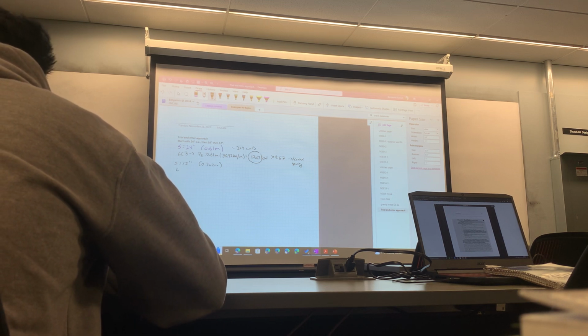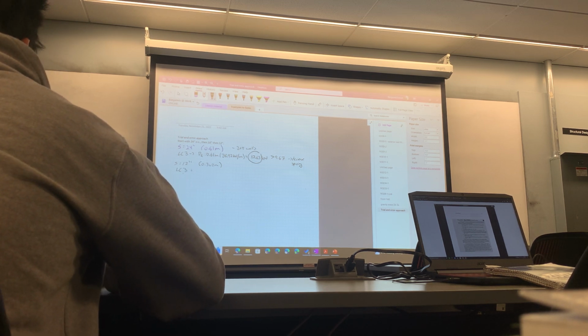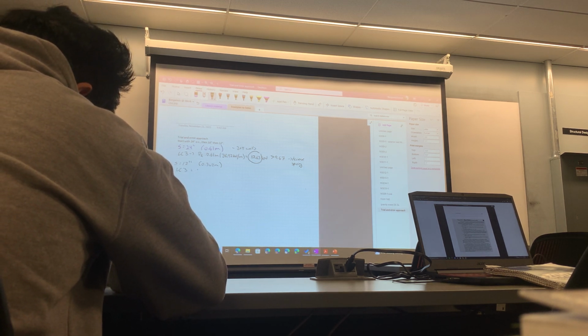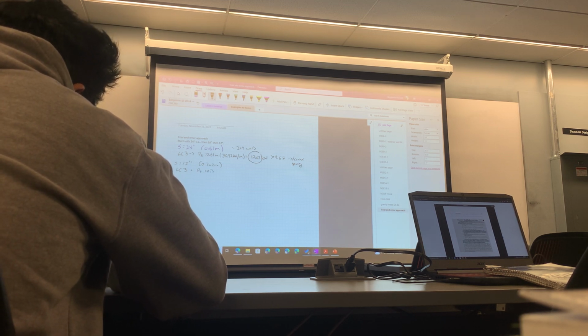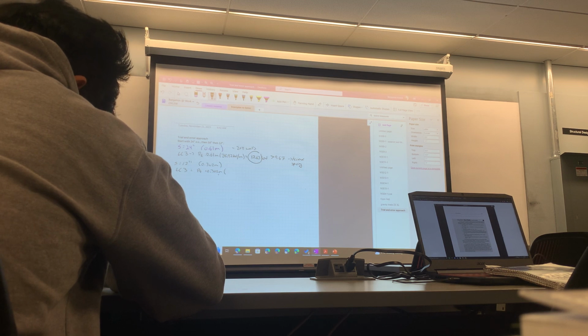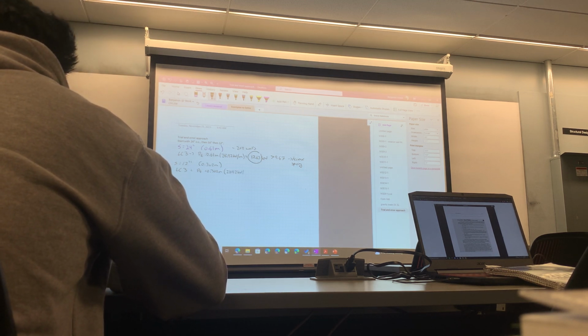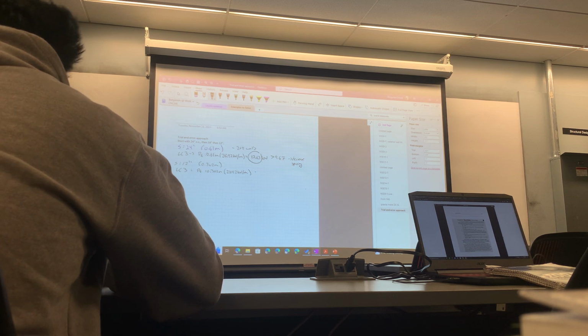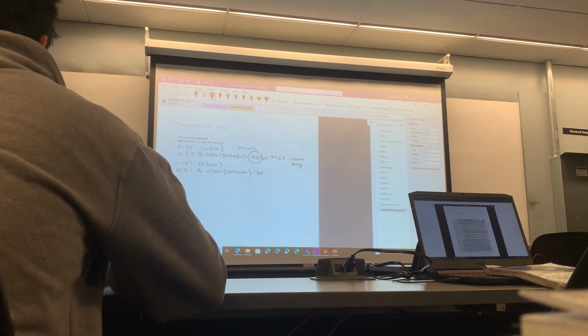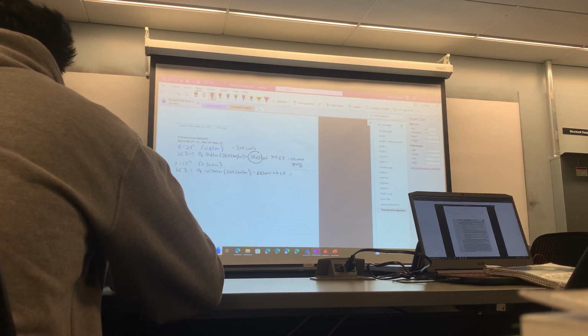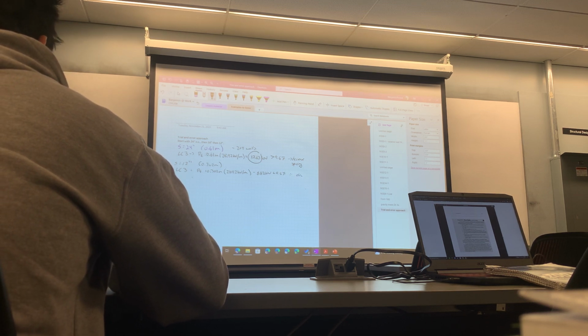So load case 3 is going to be PF equals 0.302 meters times 28.92, and that's going to be 8.82 kilonewtons, which is less than 9.67, therefore okay. Now let's check the wind.